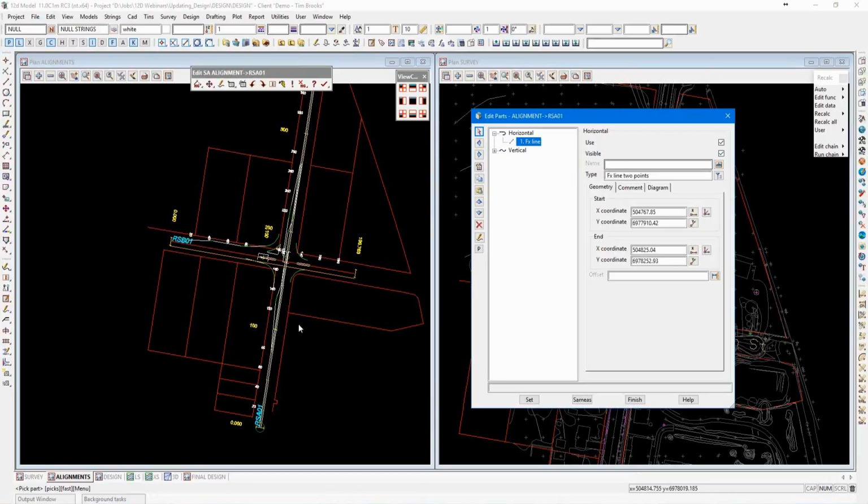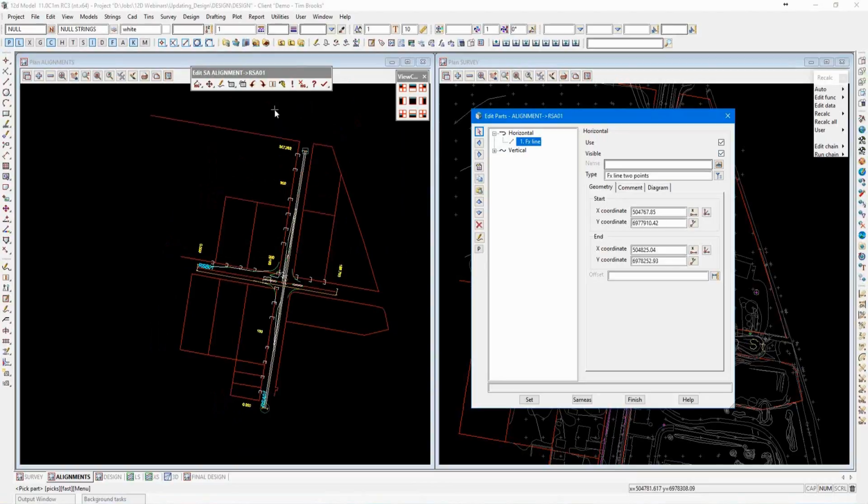Now if you were to have an alignment with many different segments, you can name those individual elements or segments. The naming of these segments allows you to reference positions inside your MTF modifiers. So simply just give it a name. Just a word of caution here, if you do name them, make sure you don't come back and change the names once you've referenced them.